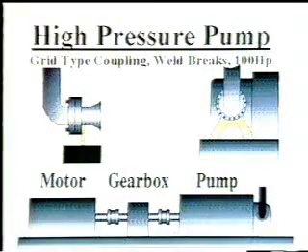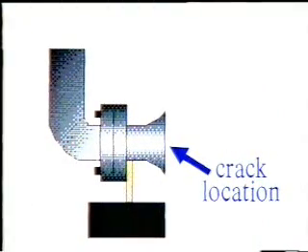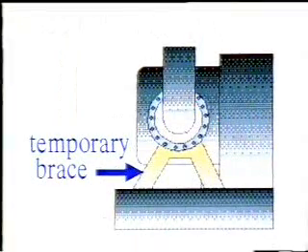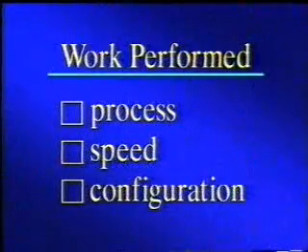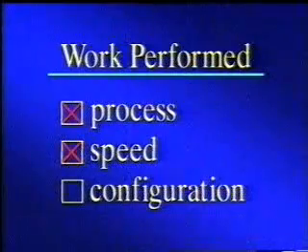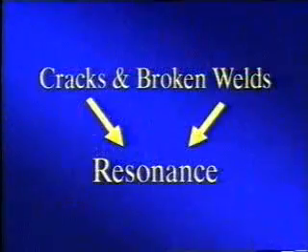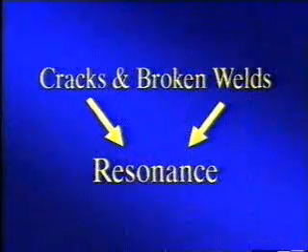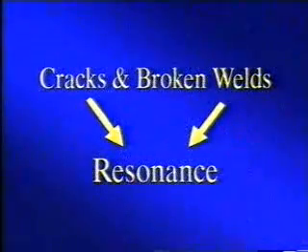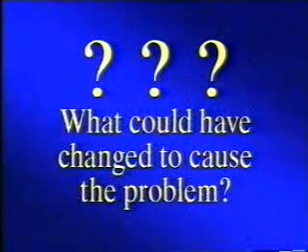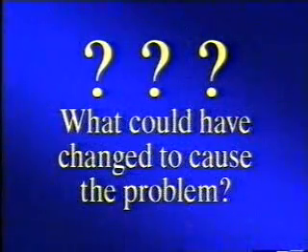A case history involving multi-channel phase data to solve a vibration problem on a high-pressure centrifugal pump illustrates the value of phase analysis. The pump header repeatedly cracked, causing a shutdown of the manufacturing process. A temporary brace was installed to help remove the strain on the header, but it cracked again. No other work has been done on the machine, and the process, speed, and machine configuration were not changed. Since cracked welds are typically indications of resonant frequencies excited from some other forcing frequency, there must have been internal changes in the machine to generate a forcing frequency.